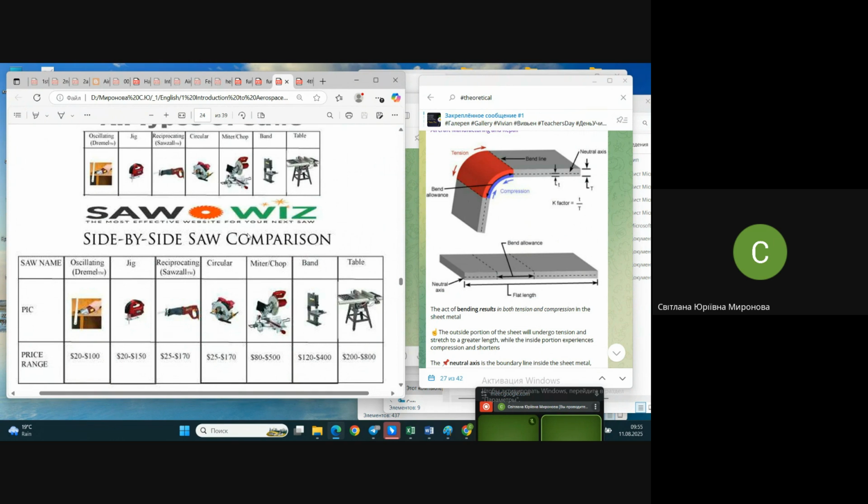The most obvious, do imagine the sheet of paper, the most obvious way to cut it. What is the most obvious? Scissors, yes. And the same we have for sheet metal. We have different machines which are called scissors. Despite simple scissors for metal, they look exactly like normal scissors we get used to see, but blades of them are much shorter and much more massive. So cutting is possible by scissors, by saw. Saw may be of different types also, and scissors may be of different types.